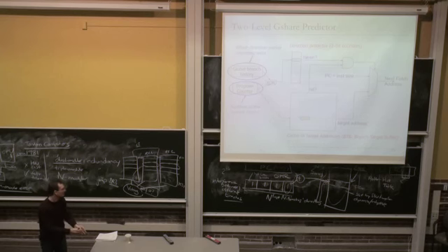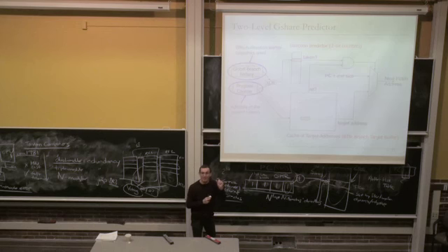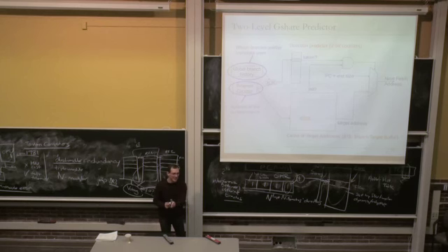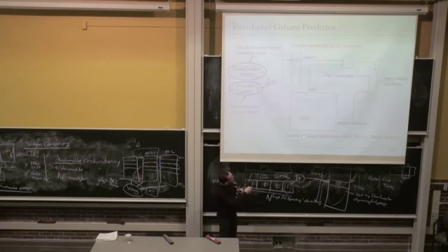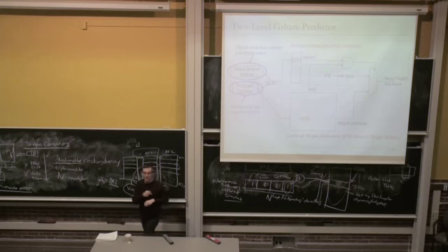So now you have context information about the indirect branch. How did you get to this indirect branch? Essentially, that's what the global history register tells you, right? What path did you take in the control flow graph of the program to get to this indirect branch? And you can record the target address you saw at that path, perhaps XORed with the program counter. And the next time you see the branch, you're going to predict the target address to be the same. And assuming there is that kind of predictability in the behavior of the indirect branch target address, you'll get it right. And it turns out this provides significantly better performance compared to predicting the target as the target of the last time you executed the branch.